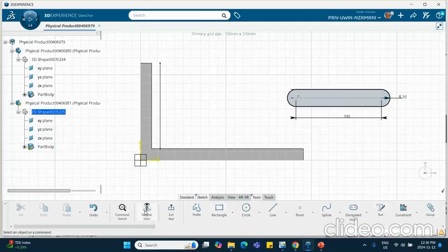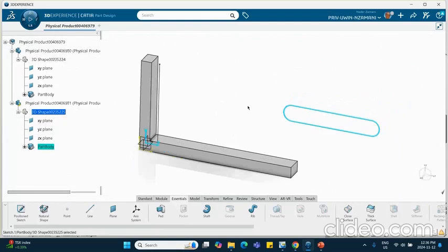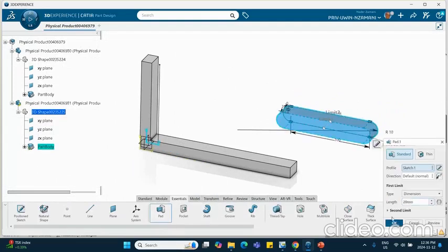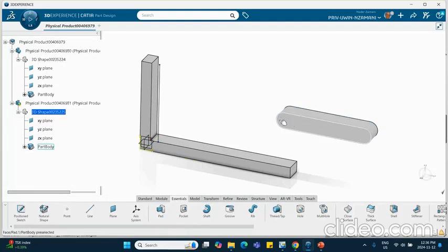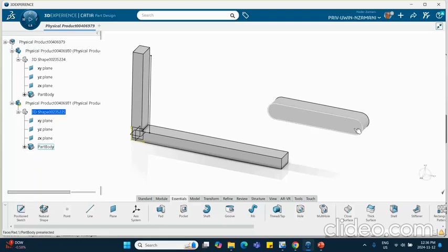Okay, exit, and we can pad this thing by 20 millimeters. Now I'm going to create 2 points here. One of them is going to be at this end. That's going to be used for point curve join, and another point down here. And the purpose of this other point is to be able to plot velocity, acceleration, stuff like that for this bottom point.